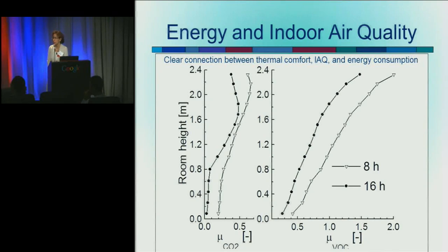And typical source of VOC or volatile organic compounds would be this lovely carpet that we have here. So that ventilation that is diluting CO2 and diluting those VOCs had resulted in a lower concentration. Anybody has a guess? Actually, it was afternoon, so solar radiation was higher through the windows that did not have shades. So the ventilation rates were higher, and therefore dilution was better.